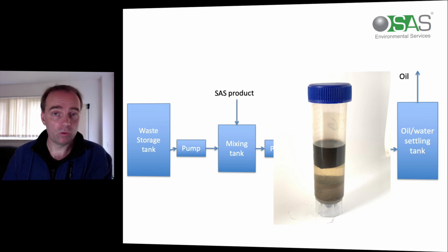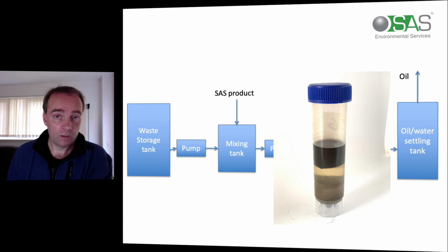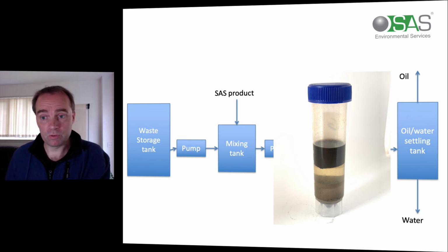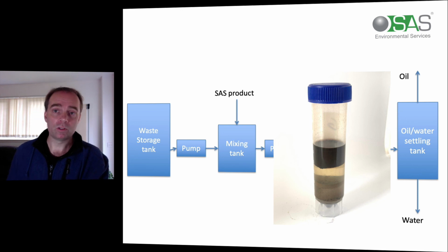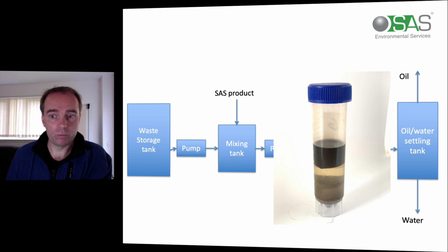You can recover this oil, you can sell it, you can reuse it, you can run a generator off it. Sometimes you might want to bring that back to the preparation stage and dilute heavier sludge that you might be treating. And at the other end, you will be recovering the water. The water can either be discharged to surface, to sewer, go to a wastewater treatment plant, or undergo further cleaning or filtration depending on where you are, and what the regulations and your permits are.